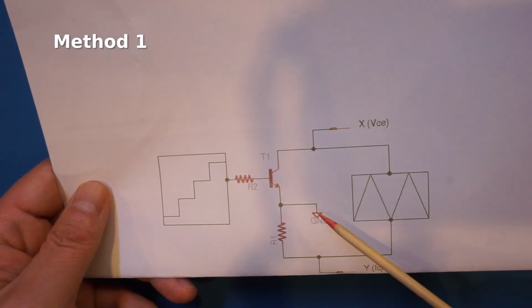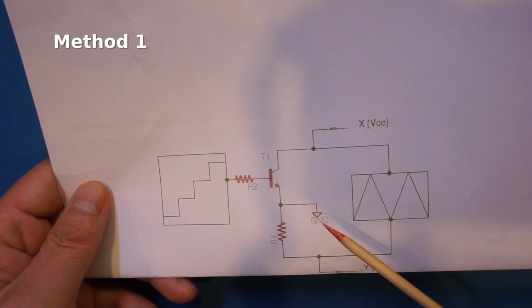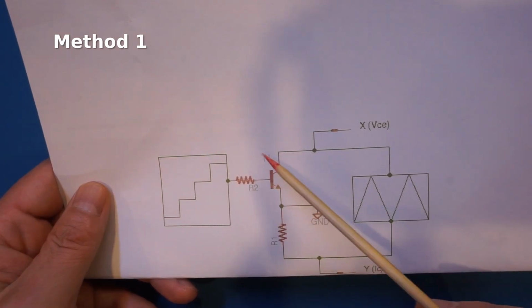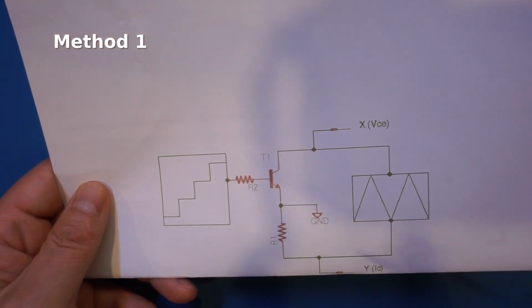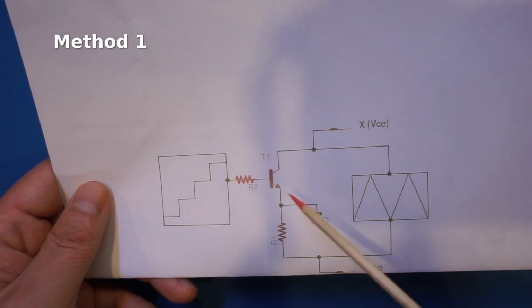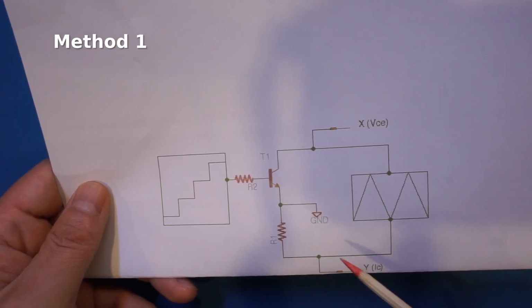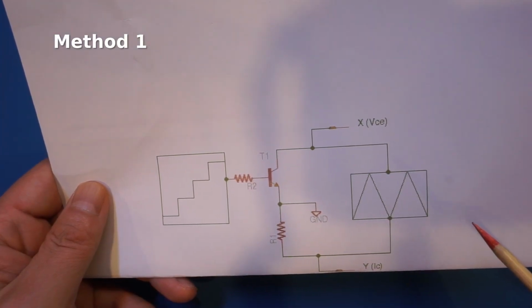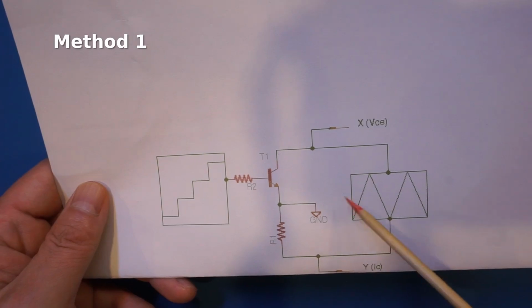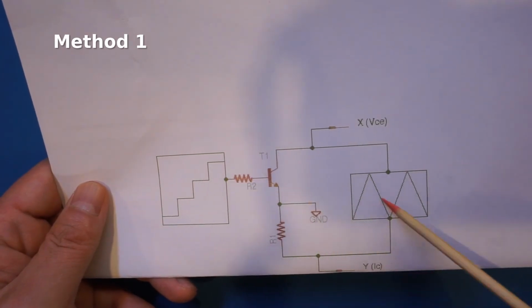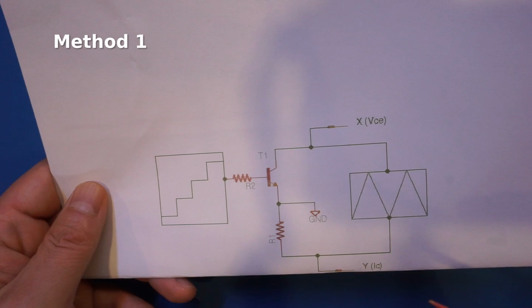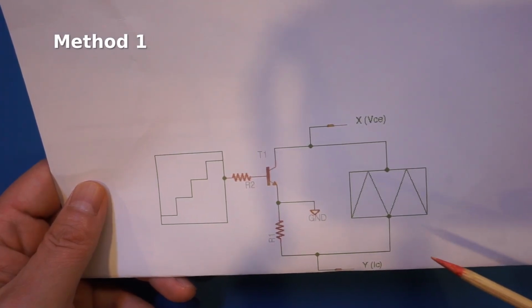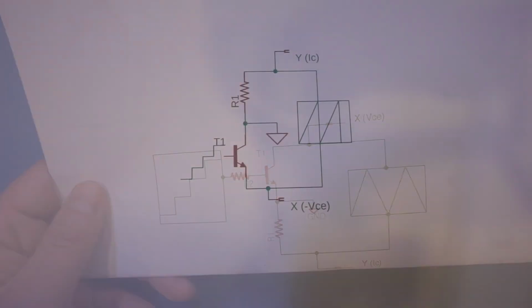The grounding situation here actually introduces another problem. In this case, the waveforms driving both the base and the collector-emitter have to stay afloat, as otherwise they will short out R1 here, so this tracer will not work. This means whatever signal source we use, we have to have isolated grounds for the different channels driving these two waveforms. Now, unfortunately, most of the cheap multi-channel AWGs do not have isolated grounds, so you will have to use multiple of them as independent signal sources.